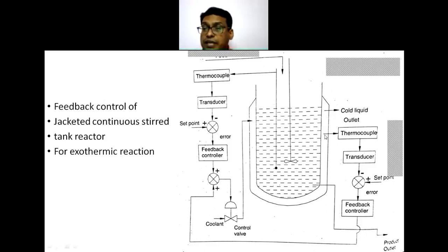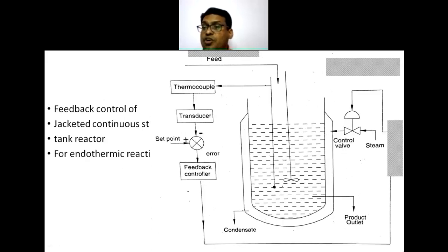However, we are not measuring the outlet temperature of the utility, the steam, in this endothermic reaction, because it is presumed that only the latent heat is being transferred. No sensible heat is being lost or given by the steam to the process fluid.